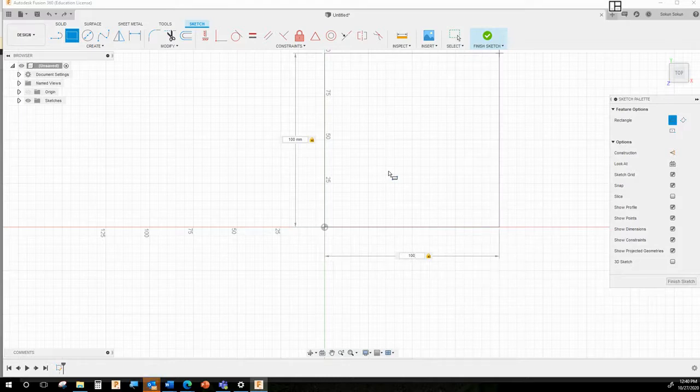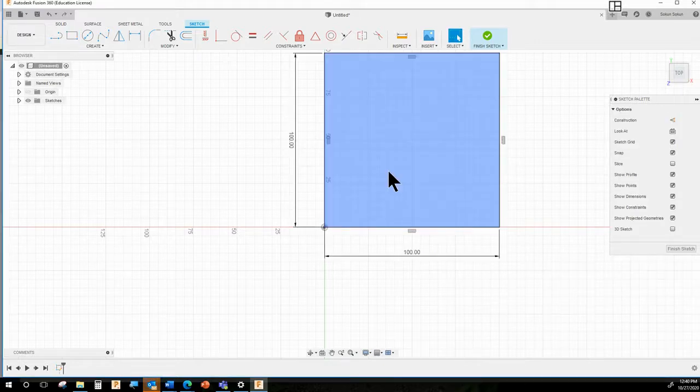And this might take you a little practice. Just practice until you get it right. Then once you know your dimensions are right, hit enter. Okay? So now you have this nice bright blue rectangle, or light blue rectangle, that has dark lines around it, which lets you know it's fully defined, which you don't have to worry about.